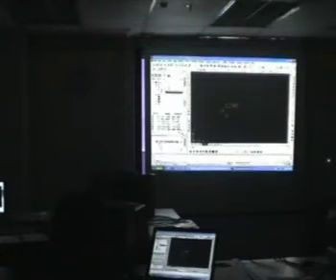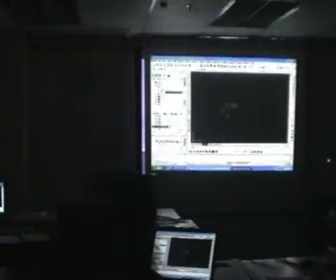If I want to modify the description for this, like just now in Land Desktop I had to go to Points, Edit Points, Modify, and so on. Here all I need to do is just click on Points, select that point, change this, let's say I put 3. Okay, modify it, right?